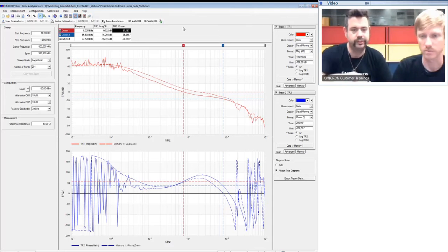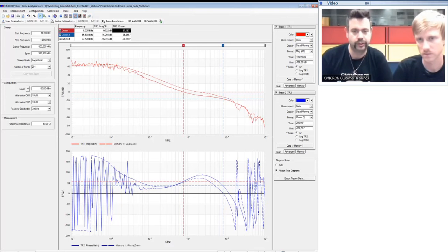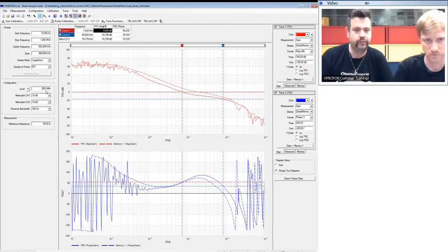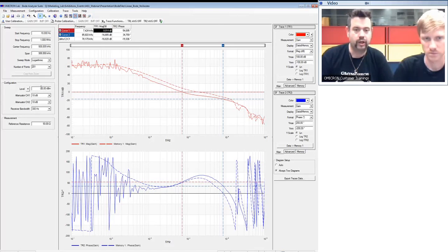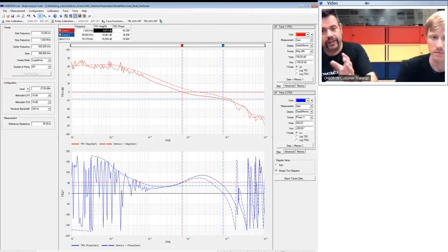And now please change to minus 25 dBm just to check if there is an influence on the pass-through point. And yes, there was a slight change. So you see it even went down further, and we are now at 54 degrees. So here we are coming into a range where the output of the Bode 100 is at the minimum. So if we go to minus 27 dBm, for example, let's see if it reduces further. But I don't expect so. No, now it is stable. So we can now just measure this curve.